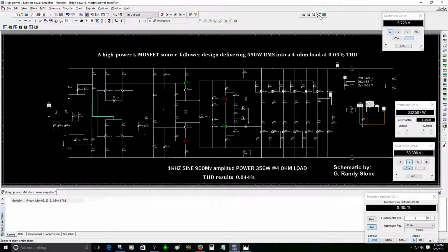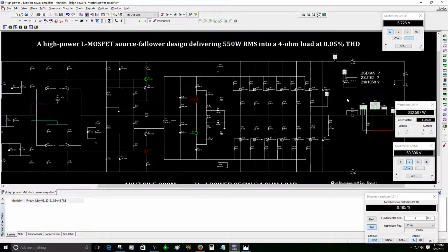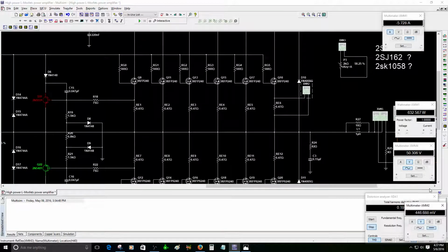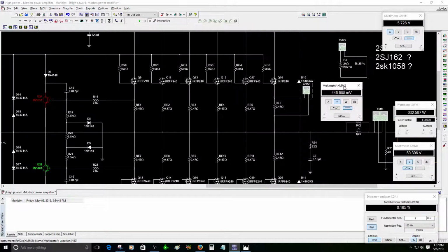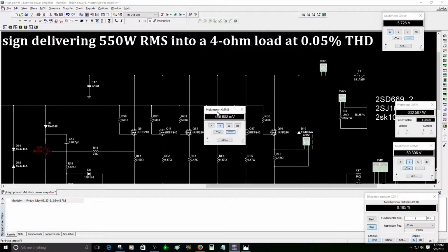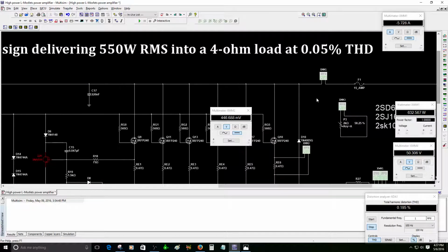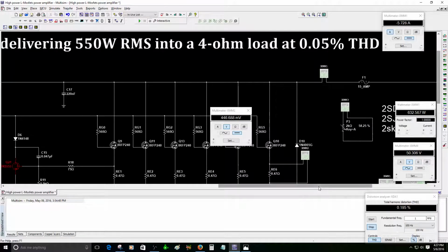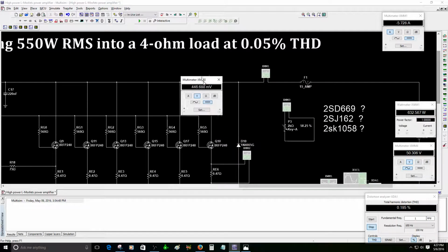Because there is a balance. You gotta have a good bias reading to lower the total harmonic distortion, but also at the same time you gotta make sure it's not conducting too much current, because it's gonna keep the power MOSFET really hot. So it's a balance that you gotta check. You gotta make sure everything is balanced. So it's difficult. It is difficult to keep that.